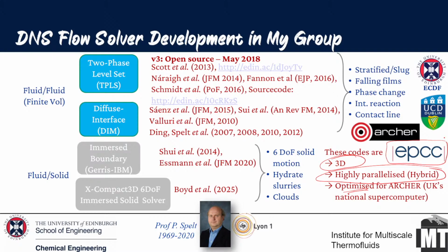They will also advise you on some of your internal methods. So for example, we had a pressure solver, which was not great. They completely changed it to the conjugate gradient method. They are also aware of better numerical methods to make sure that you can maximize the speed. Okay, so initially there is a lot of effort put into optimizing your code, but it reaps rewards later on, because you don't need to do it later on. And you can access as many cores as possible.